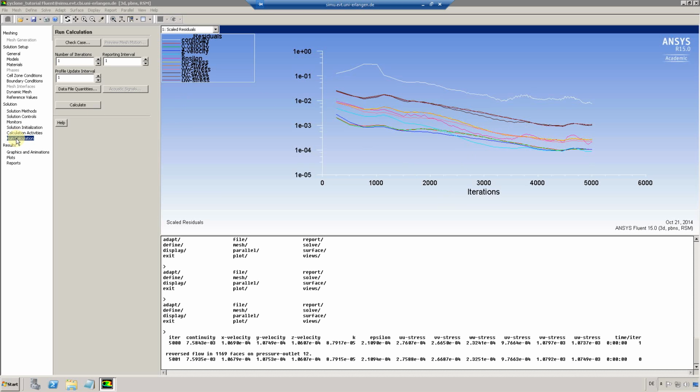Now for my master thesis, I've modeled several different topologies, which most of the time were a lot more complex and detailed than this simple standard cyclone. And I hardly ever got convergence of the solution when using the Reynolds stress model. Now what I usually do is to switch here from a steady simulation to a transient one. But before changing any settings, let's save the current time step.